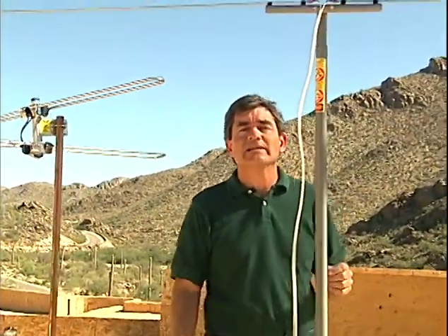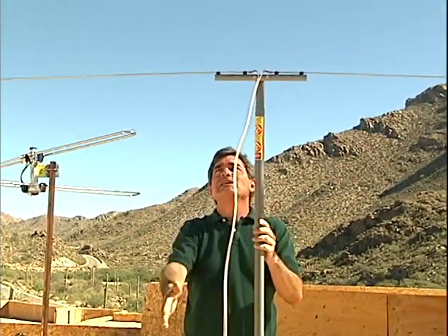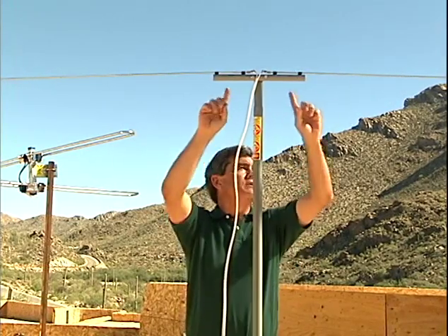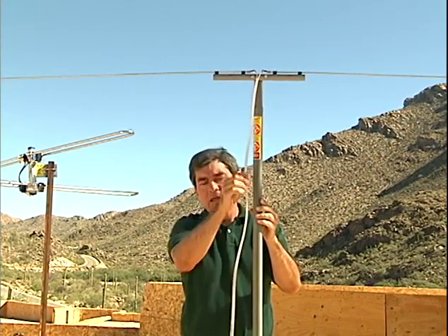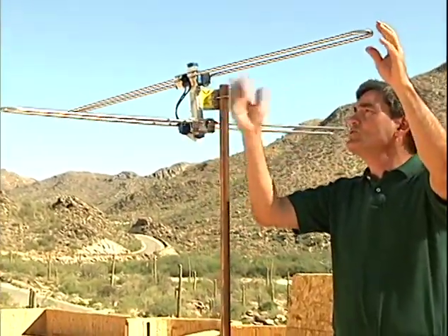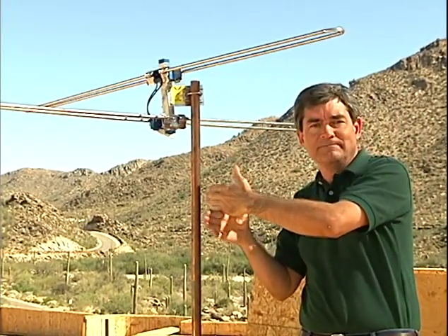Now, the best and simplest example of a bidirectional antenna is this dipole antenna, as it's called. It receives equally well from two opposite directions. It's a single element about 1/2 wavelength connected in the center with the connecting cable. Now, this omnidirectional antenna is actually two bidirectional dipole antennas connected perpendicular to each other.